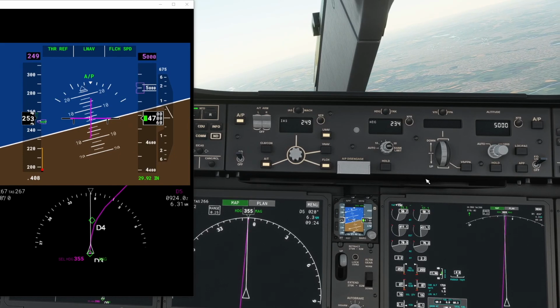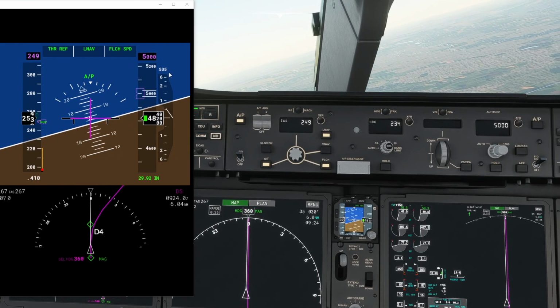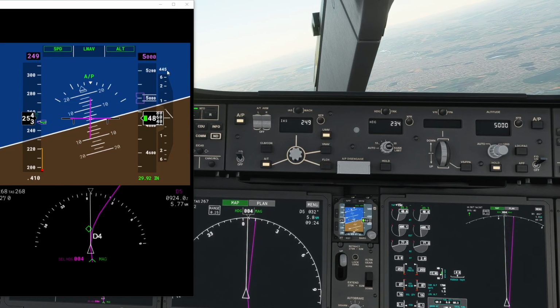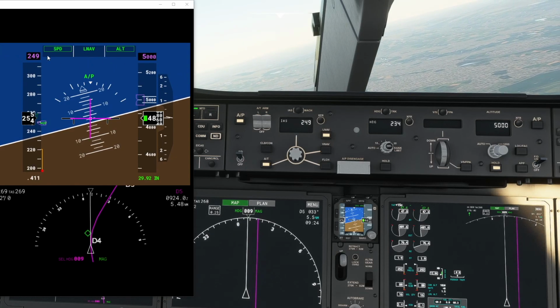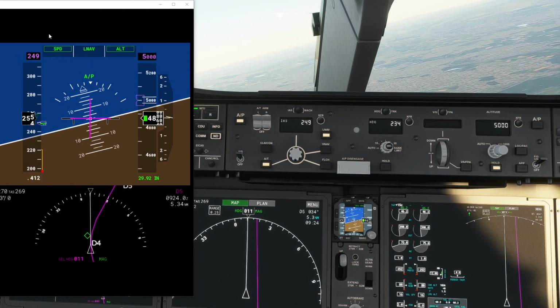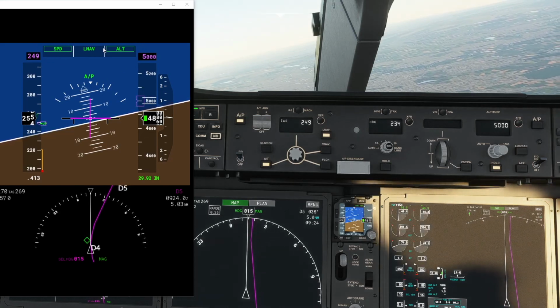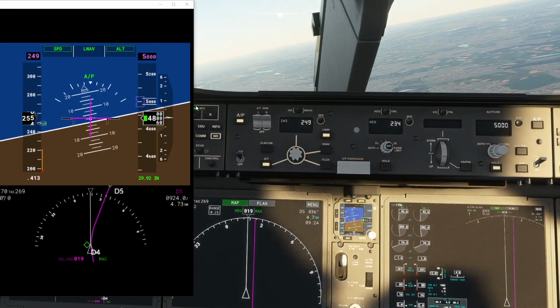There we go guys. So we're now following our flight plan and we're leveled at 5,000 feet. I've transitioned now to the en route climb. Before we do that, we've just leveled at 5,000, I'll just show you the flight mode annunciator. The autothrust is in speed mode, and the pitch mode is in ALT hold at 5,000 feet.